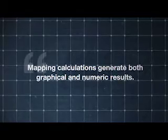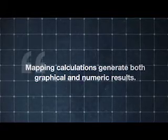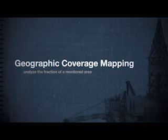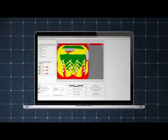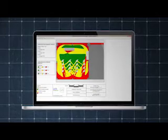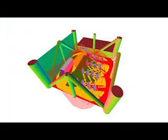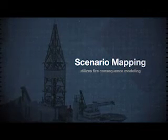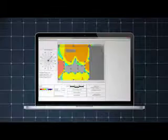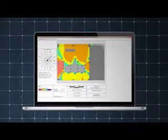Mapping calculations generate both graphical and numerical results and can be performed in one of two ways: geographically or scenario-based. Geographic coverage mapping is used to analyze the fraction of a monitored area where hazards are detectable. The results of geographic mapping are color-coded coverage maps, where the coloring represents the number of detectors monitoring any given area. Scenario mapping utilizes fire consequence modeling, or gas dispersion modeling, as an input.